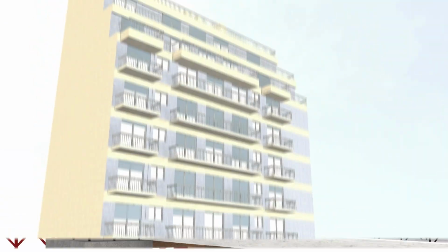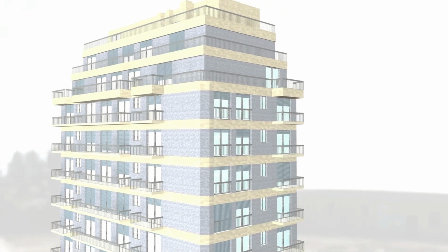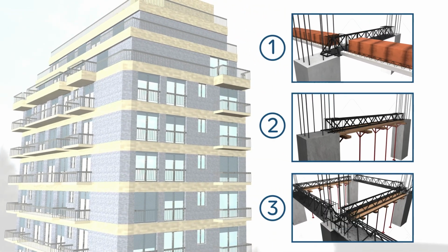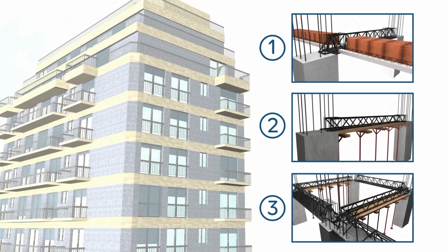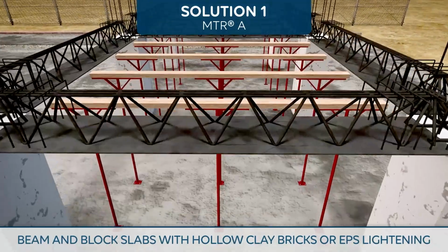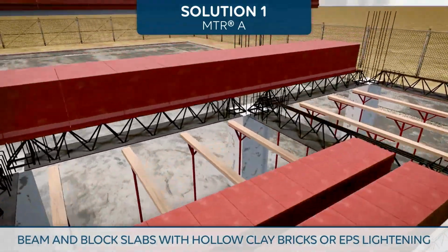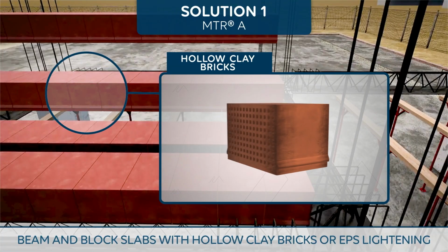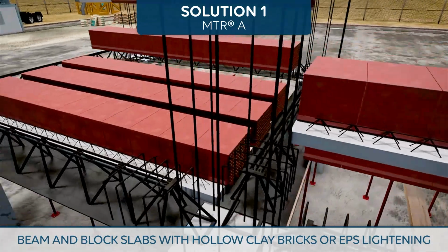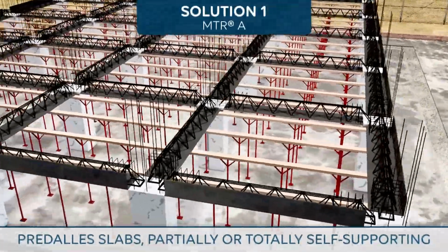For residential buildings, MTR A offers three solutions for the total prefabrication of the horizontal structures, aiming to keep consistent the thickness of the floor. Solution 1, totally self-supporting, consists in the use of MTR A beams only, combined with different types of floor, such as beam and block slabs with hollow clay bricks or EPS lightening, predal slab, partially or totally self-supporting.